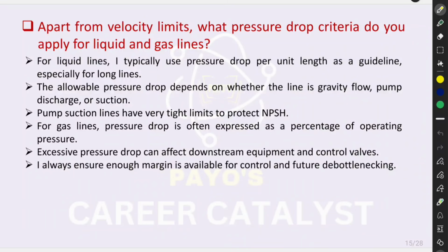For gas lines, pressure drop is often expressed as a percentage of operating pressure. Excessive pressure drop can affect downstream equipment and control valves. I always ensure enough margin is available for control and future debottlenecking.